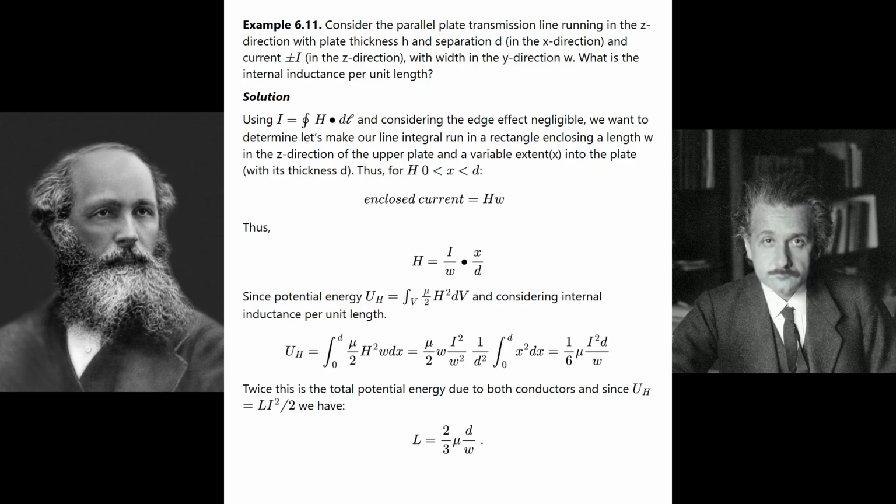Solution: using I equals the contour integral of H dot dl and considering the edge effect negligible, we want to determine H. Let's make our line integral run in a rectangle enclosing a length w in the z direction of the upper plate, and a variable extent x into the plate, with its thickness d. Thus, for d less than x less than d plus h, [equation]. Thus, [equation].